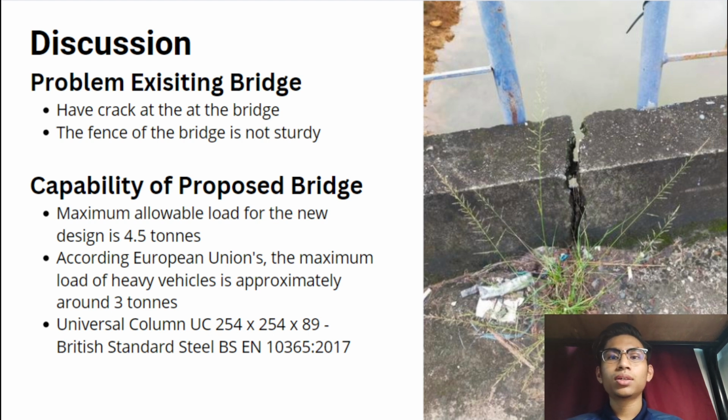We are using universal column UC 254 times 254 times 89, which refers to the British standard steel, which is a suitable material for this proposed truss bridge due to the load that occurs on that structure.